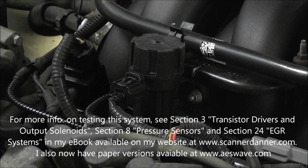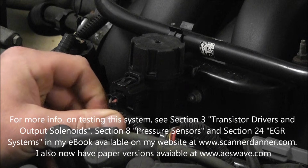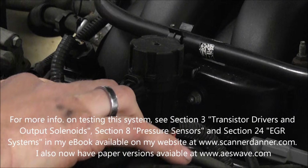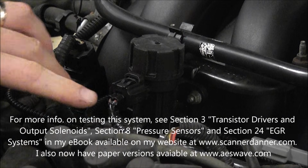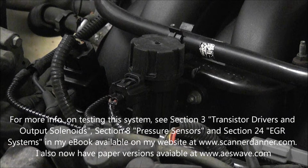And what we can do, two things. We can look at the wiring diagram and figure out which one is the feed and which one is the control. I've got a real heavy red wire, and then a brown one, I can't really see the color of that too well without my flashlight, but I know these Fords well enough that it's the smaller gauge wire that is the control wire. And again, I'm using a test light to ground, so if I accidentally T-pin the feed wire, all I'm going to do is light my test light. I'm not going to hurt anything here.